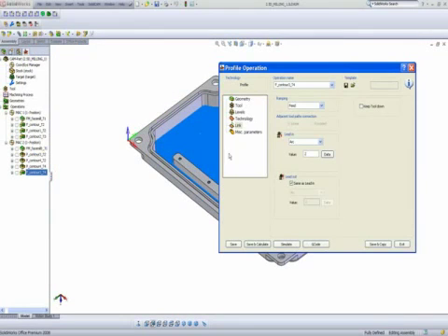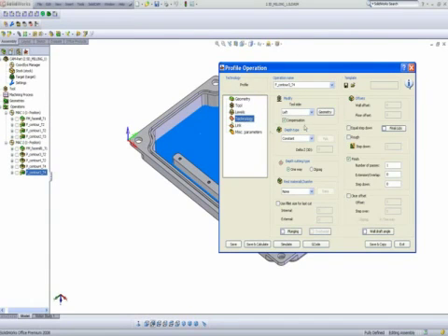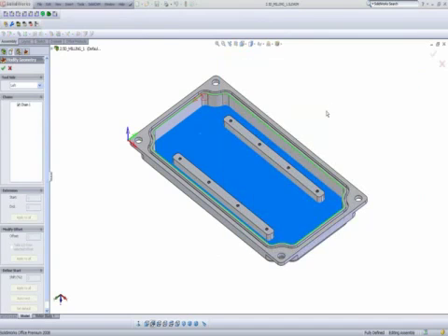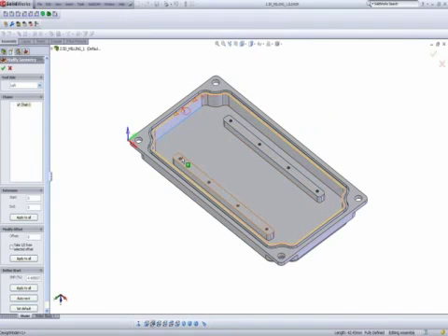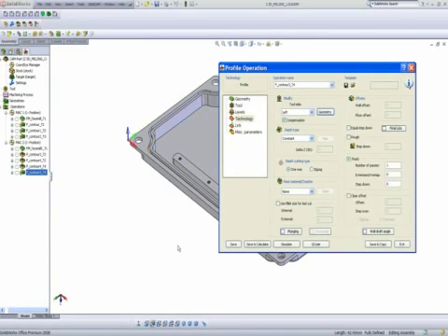This can simply be done by going to my technology area into Modified Geometry. In Modified Geometry, I simply click on the chain and say, OK, define start. If I click into that window, all I have to do is click in the area where I want to have my start point, accept it, and just simply save and calculate.